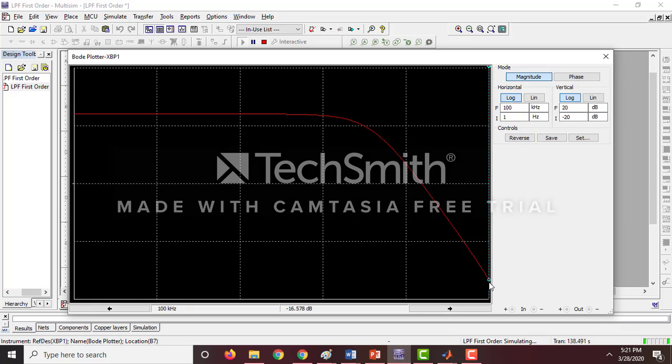This is why I told you in the class that a first order filter will have a slope of minus 20 dB per decade. So frequency here is 10 kilohertz, this is 100 kilohertz. Here what was the value? At 10 kilohertz the value was around 3.4. Here it is around 16, which means minus 16, which means the gain has reduced by 20 dB almost. So you can see that the slope is 20 dB per decade.